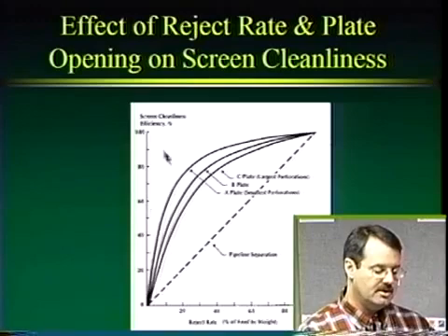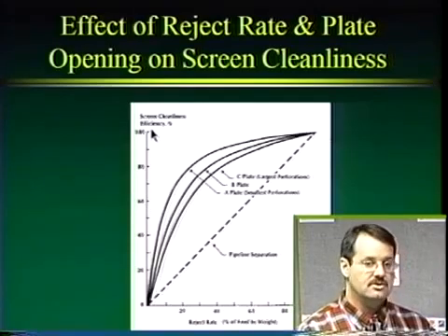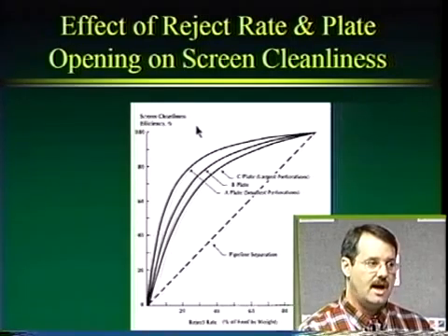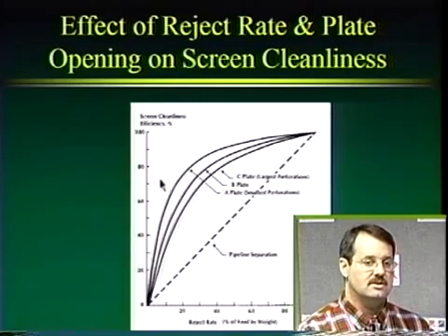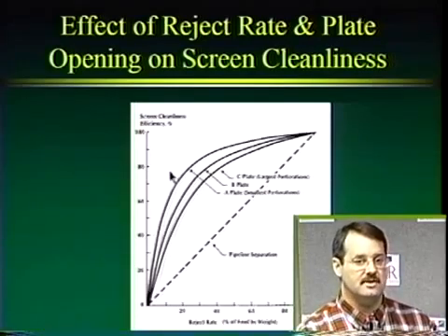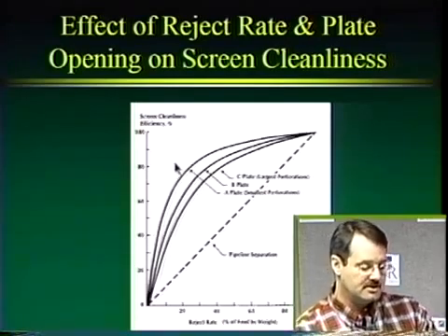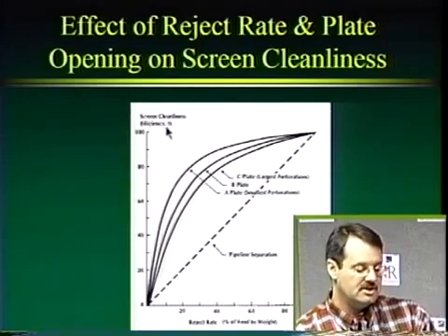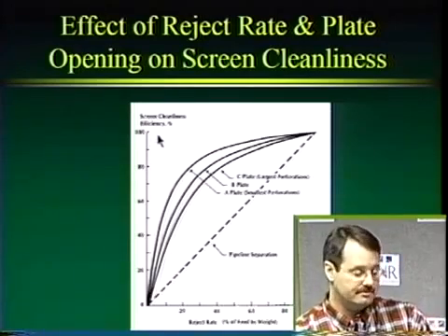That's the concentration of contaminant in the feed, in parts per million, minus the concentration of contaminant in the accepts, divided by the concentration of contaminants in the feed, just like last lecture. So it tells you the reduction in the concentration of dirt.